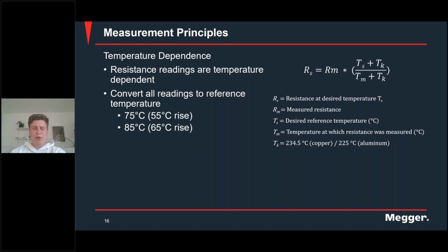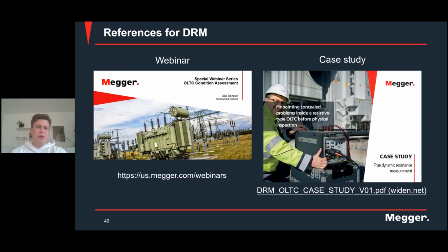So step voltage regulators is something that you have in the US and we don't have here in Europe. But from my understanding, it's an auto transformer, and you have connected a reactor, a preventive auto tap switch to part of that auto winding. So yes, they should be able to be tested with the same methodology that you test the reactor OLTC on your power transformer.